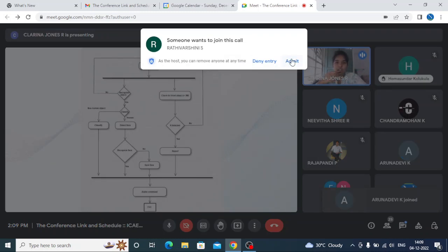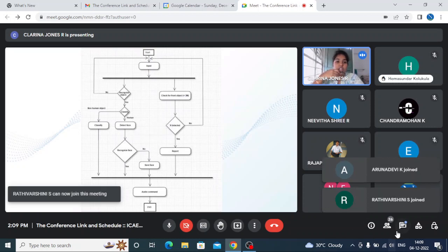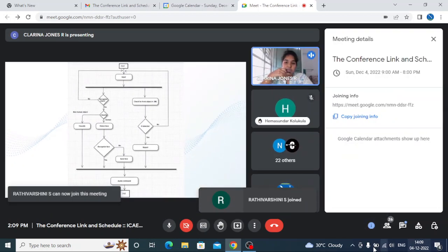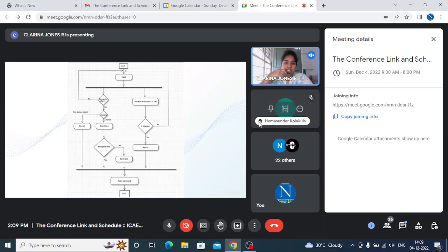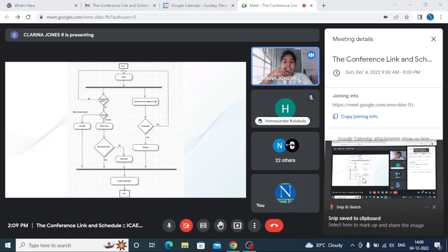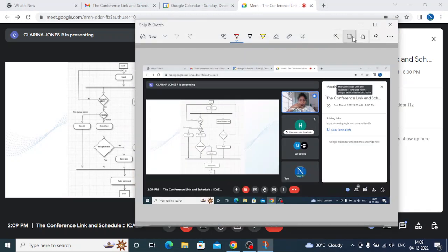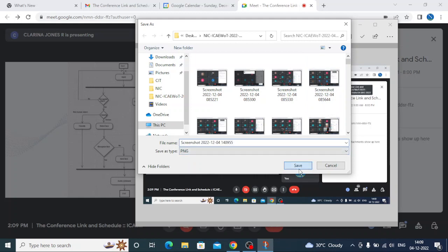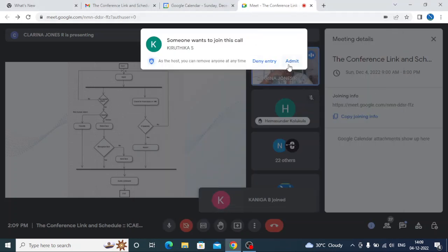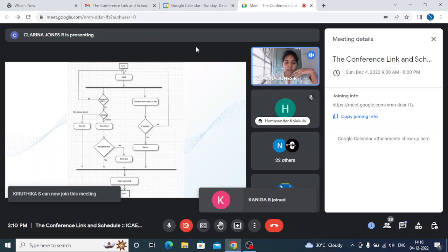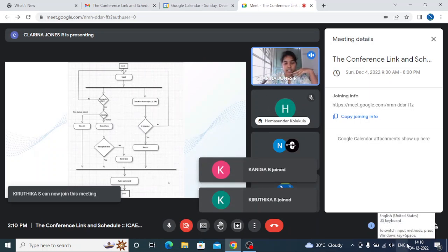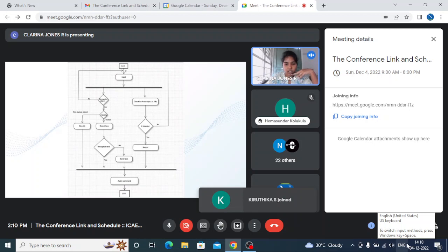So this is the flowchart of the working principle of our project, sir. When the user wears the glove and starts moving, the system starts and checks for any upcoming hindrances. If the ultrasonic sensor detects one, it reports to the vibrator device to vibrate, and an audio command is given to the user. Simultaneously, if the Pi camera recognizes an object, it starts its classification process. If the object is human, it recognizes the face and sends a signal to the user as a voice command, and if a non-human object is detected, it classifies it and also sends an audio command to the user, sir.